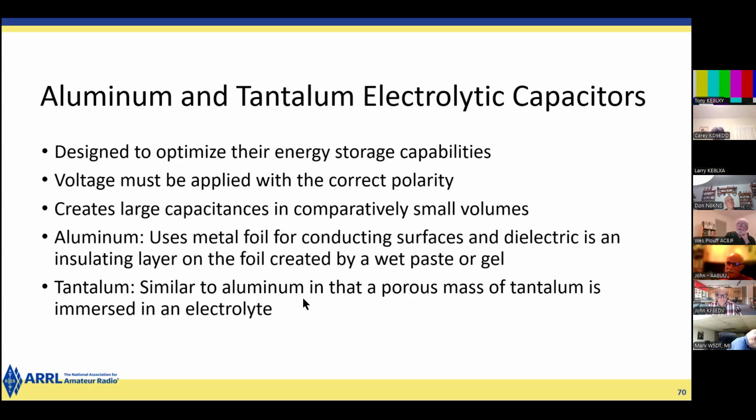Yes. And there's another thing you should know about electrolytics. If you talk to people who restore old radios, the first thing they'll do is replace all the electrolytic capacitors. Because if an electrolytic capacitor isn't used for a long period of time, if it sits on the shelf for a few years, then the dielectric film won't form when you apply a voltage to it. Instead you get a short circuit.